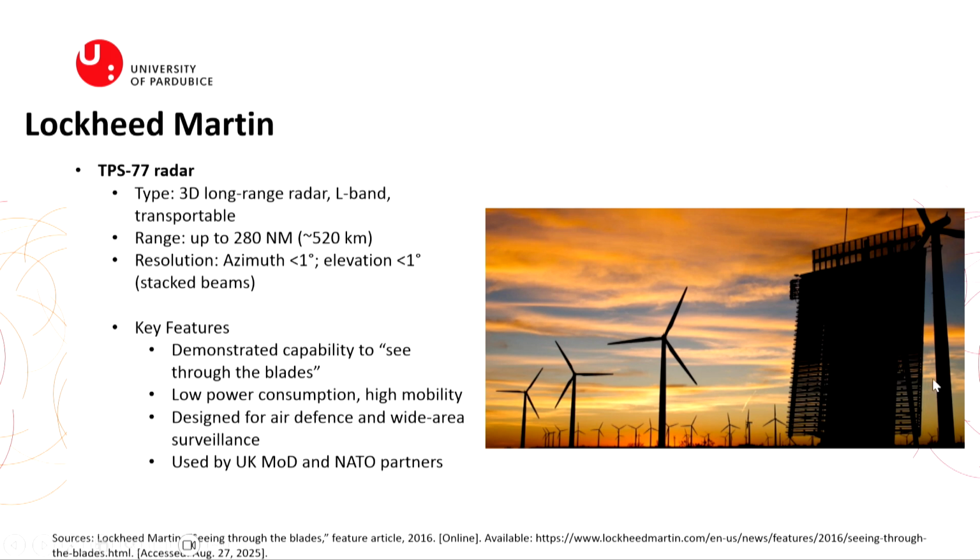It is transportable, so it is not so huge. Range up to 300 nautical miles, so about 500 kilometers. It must be huge, powerful. And azimuth resolution under 1 degree and elevation also 1 degree. It is impressive parameters for such a long-range radar.